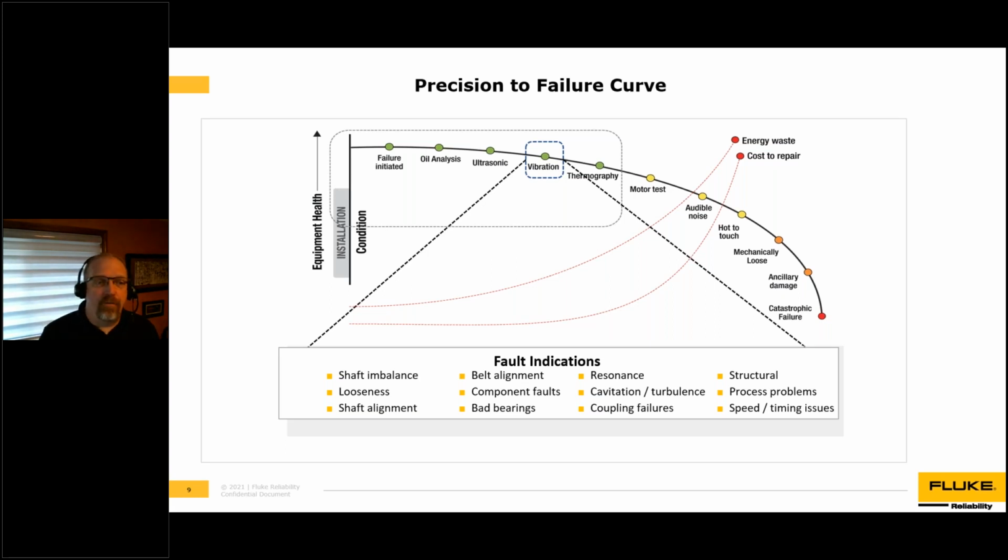In the Goldilocks zone, we have vibration analysis. Vibration analysis can inform us of a wide range of issues months in advance. This allows analysts to track the severity of faults and determine the best way to respond to the issue. In addition to traditional vibration analysis, this can include tools like motion amplification and modal analysis. The comprehensive nature of vibration analysis provides valuable tools in identifying the root cause of mechanical faults.